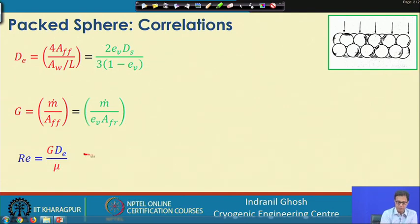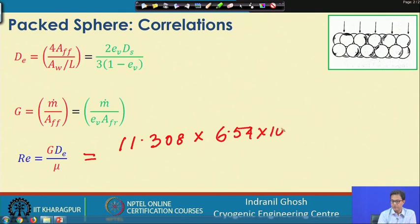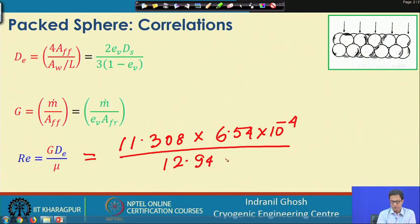So, if we put G equals 11.308 multiplied by the equivalent diameter 6.54 into 10 to the power minus 4, and mu equals 12.947 into 10 to the power of minus 6, we get the Reynolds number to be 571.